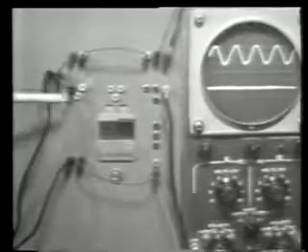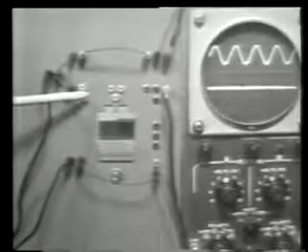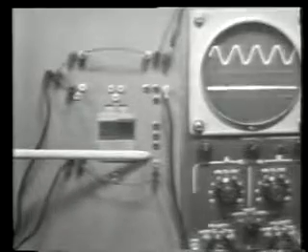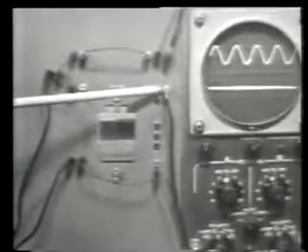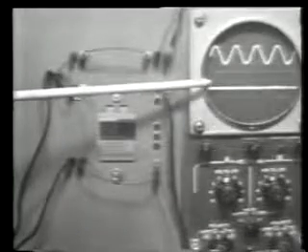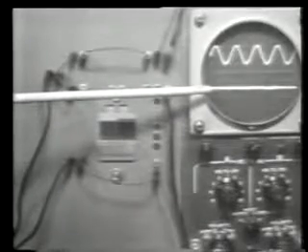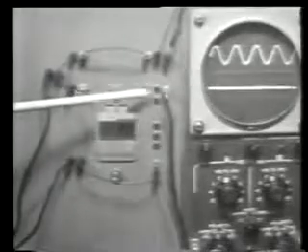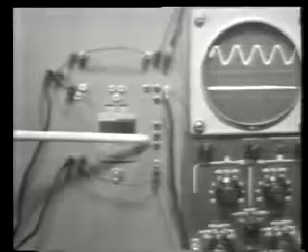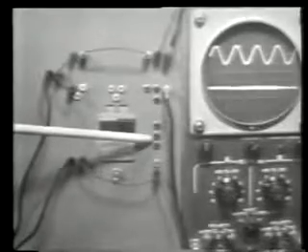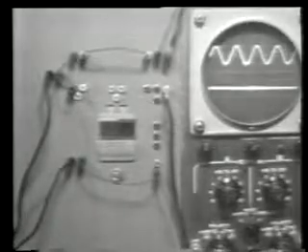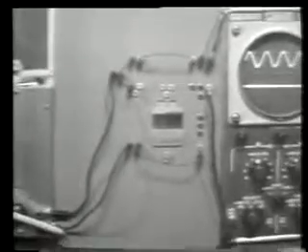Now the lower connection here, this is where we'll connect our filter components. The series component here, the shunt component here. We'll take our output across the shunt component and it will be displayed on the B trace or the lower trace of our oscilloscope. Now as you can see, we have no output at this time because of course we have no components plugged into our filter circuit. Notice also that the oscilloscope, a little trainer, and the signal generator are all grounded together.